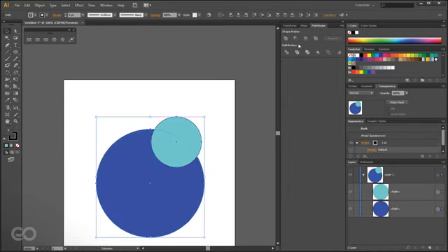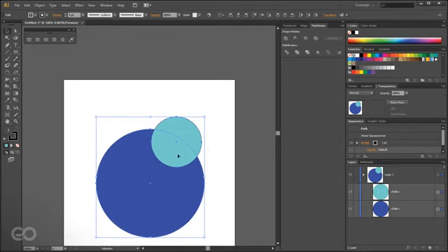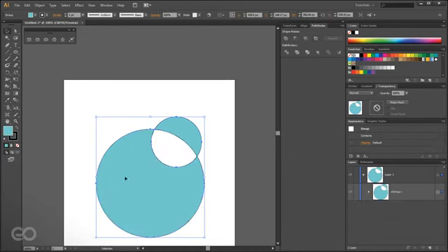Similarly, let's say I wanted them to intersect. Basically give me only the exact portion where both of them overlapped. So that gives me intersection over here. Apart from that, you have reverse intersect, or what is it called, exclude. If I click on this, it gives me all the portion which is not being overlapped by both of these two objects. So these are the different ways you can basically work with two objects.